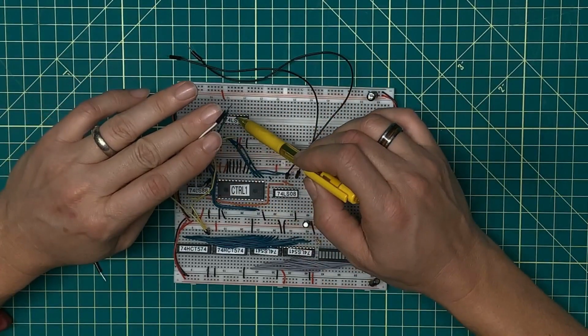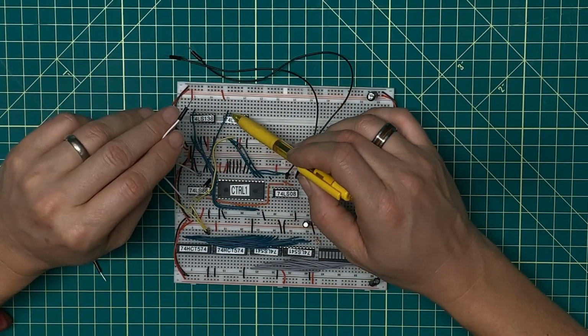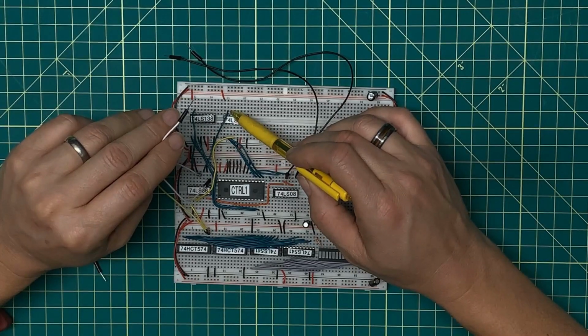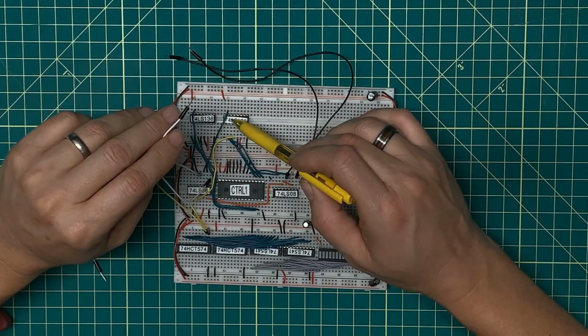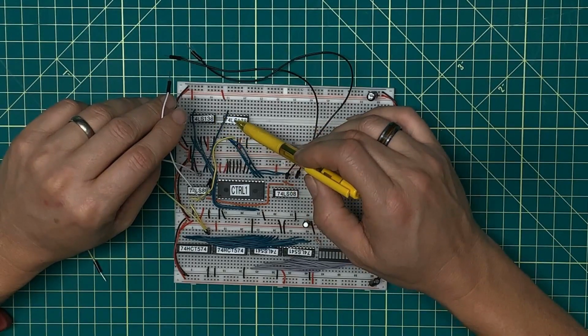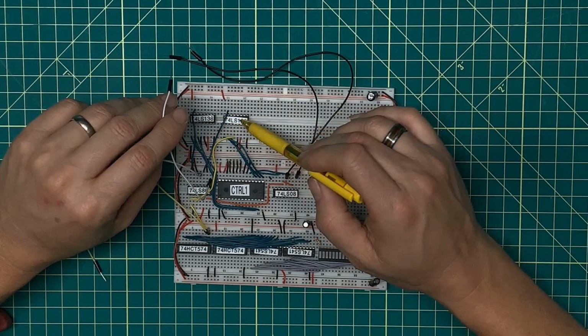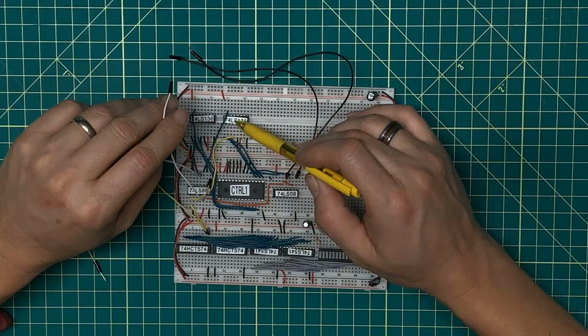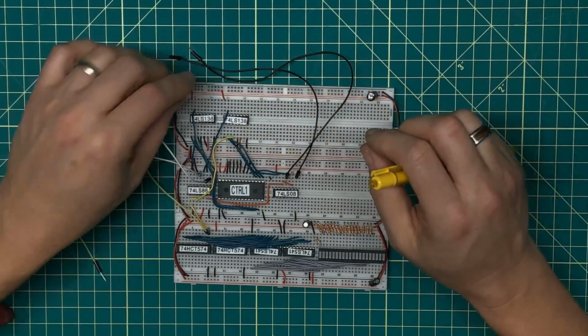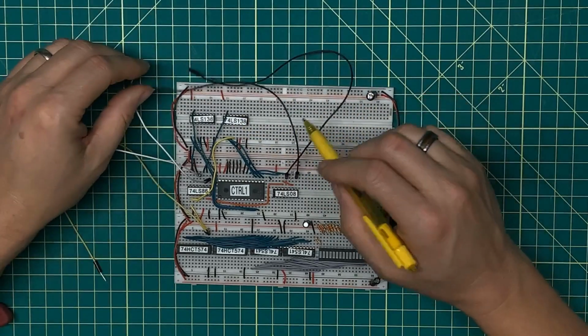This is the AND latch signal, and this has also gone through a demultiplexer, and output 0 is to latch the program counter. So once again, if I have 0 and 0, it means that my program counter is asserting to address bus 1 and latching at the end of the increment. Now the increment is not quite so straightforward.